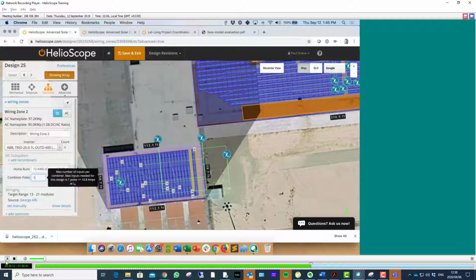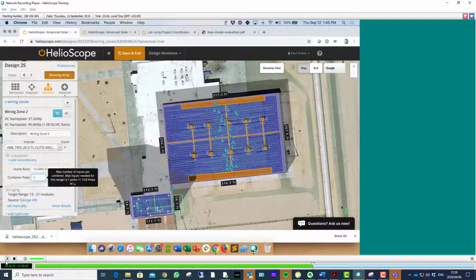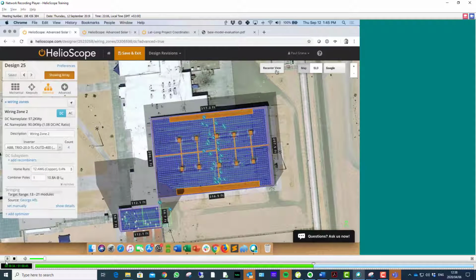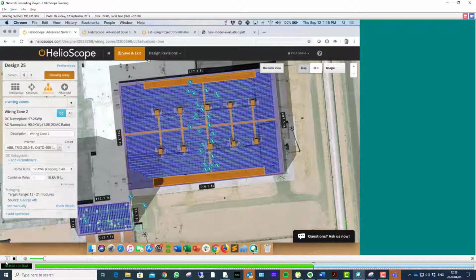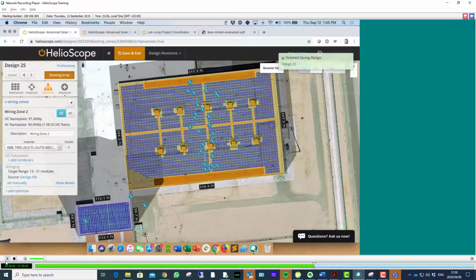So when you do have east-west, it is going to do its best to keep those on different azimuths. Although you can, of course, construct a system where you don't allow that to happen, just because it's a really small system and it kind of forces them all into one string. So it's not foolproof, but if it can, it will keep the azimuths separated on an east-west system. Cool. Awesome. So that's just a quick note on the electrical side. And with that, we're pretty much done. So now let me remove those combiner boxes, hit save and exit, and we're finished with our design.